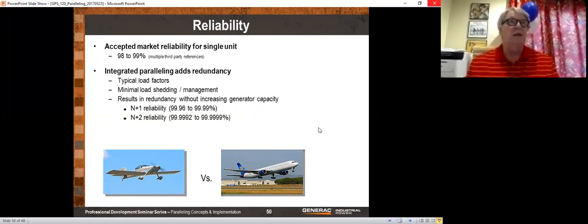That's because if we look at dollars per kilowatt, on a diesel generator it is lowest in the 400 to 600 kilowatt region. So below 400 to 600 kilowatts, it costs you a little more per kilowatt to generate that kilowatt. And as the generator gets larger, you get a lower dollars per kilowatt. Once you go above 600, now you're talking about what we call big iron, things that are not commonly used in over-the-road trucks and front-end loaders and so on. And so you end up with a lot of handwork, the profit margins are higher, and your dollars per kilowatt then goes up.